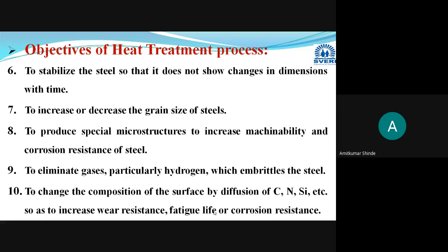To avoid these changes in dimensions with time, we do the stabilization of that steel. This stabilization can be achieved by performing different heat treatment processes.